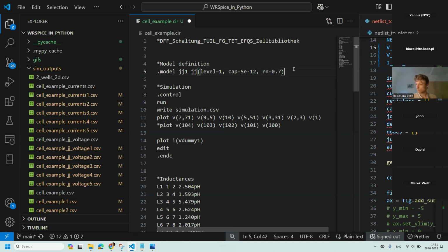And then the level 1 probably is associated with a certain technological process, because you are talking most likely about rapid single quantum flux electronics, right? This is what you do. You refer to it. Yes. Well, actually, I would say single flux, but the name is resistively capacitively shunted Josephson junction, because it's not the name of a technology, it's the name of a model. Yeah, RCSJ stands.